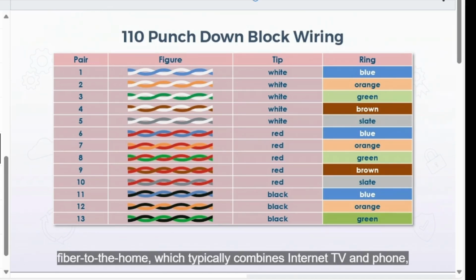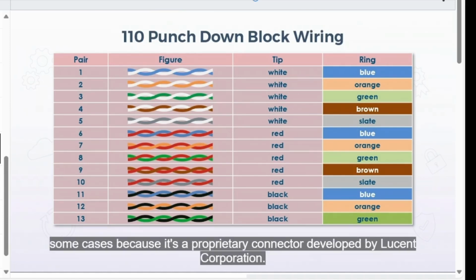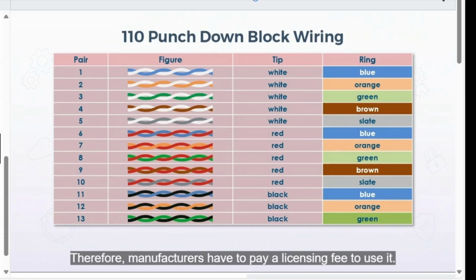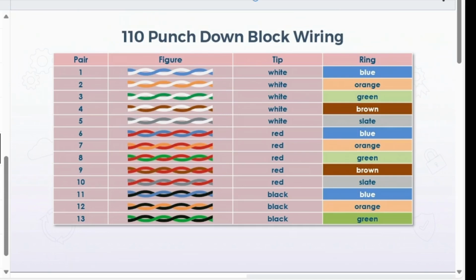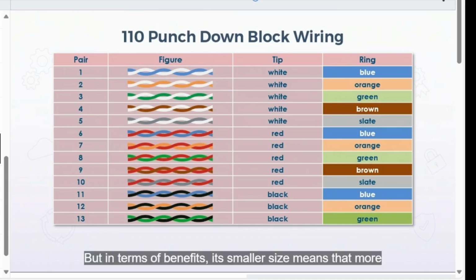For example, white and blue, white and orange, white and green, and white and brown. Then simply connect the other cable to the other side with the matching color configuration. If you also happen to be working with other cable, then in fact, they can also be connected within the same block because each connector on any given side mates only with its counterpart on the other side.